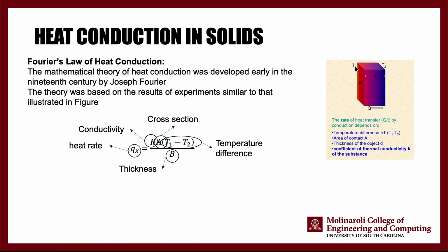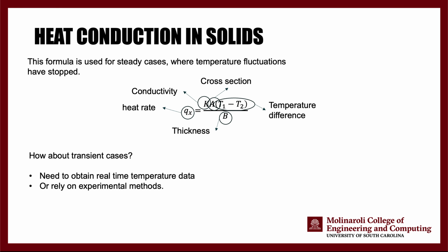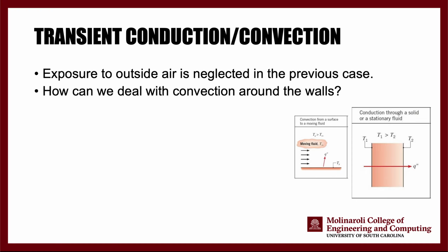And you're going to see later on how that becomes important when we are running our heat transfer test. Okay. And the idea in the lab would be for you to measure all of these temperatures. You are going to know the heat rate, and your goal would be to calculate the conductivity of your specific sample that you're using in the lab.